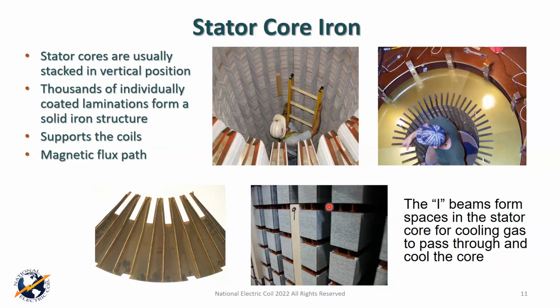So in most cases, OEMs and repair houses, in the stacking operation, will have several points at which they consolidate the stack, or press that stack together, usually using high pressure hydraulics and some special tooling. That way, when they get to the top, like you see here, and do the final compression, the core was pretty much consolidated along the way, and it's not such a big deal.